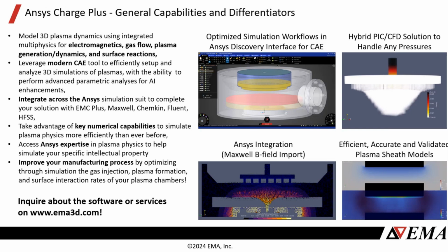I think for thin surfaces, we have various workflows. Ideally, you can just define the thickness and the type of material and do the stack up in the UI, and the solver generates that stack up automatically. The other way at this time in the user interface, I think, would be to actually resolve each thin layer like you are proposing, and then define an extrusion or thickness and material property associated to each layer.